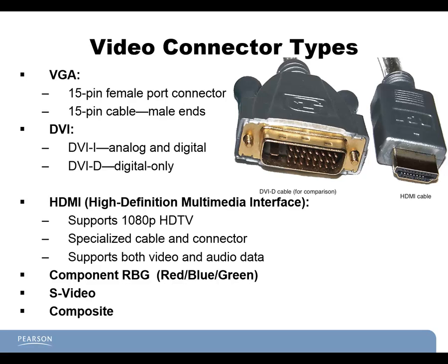If you want to display your computer on a TV, and your TV has HDMI, but your computer only has DVI, you can buy a DVI to HDMI cable, and you will get video out from your computer to your TV, but you'll need a separate cable for audio.